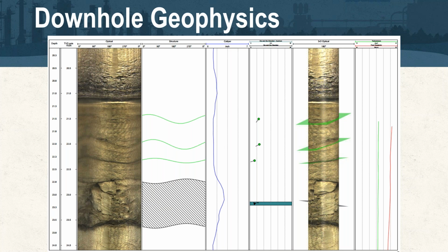At times the core location can deflect, or the reaming bit can deflect, and essentially you have a cut in the sidewall of the borehole that prevents getting a suitable seal.